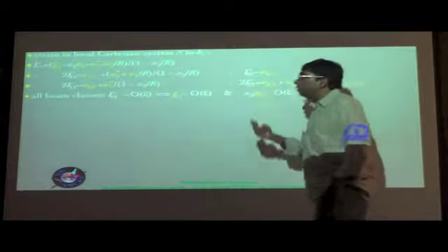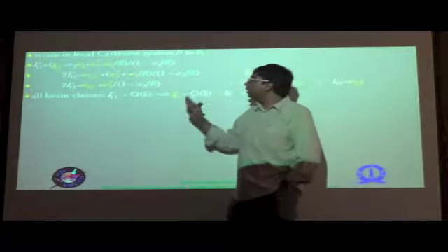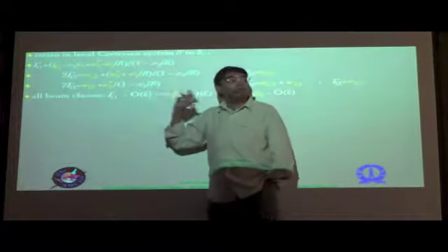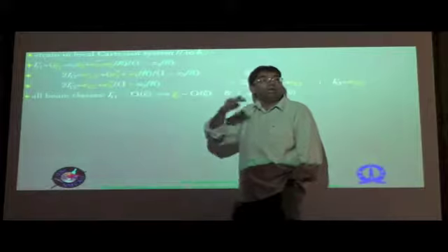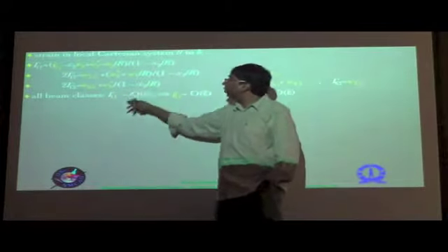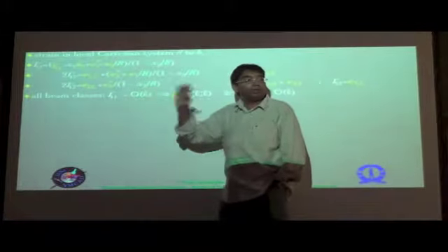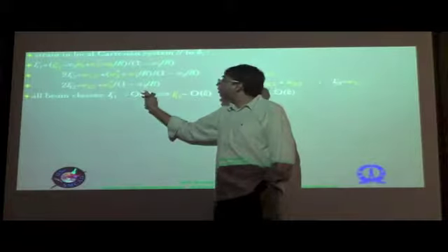Next, for all beam classes, your gamma 11 is of the order of epsilon hat. That's something which we have taken for all the strain measures, in fact. We are considering a term gamma 11 amongst all the gamma ij's right now. Out of the 6 terms, gamma 11 should also be of the order of epsilon hat at the most, right? It could be smaller than that in some specific examples, but it cannot exceed that.